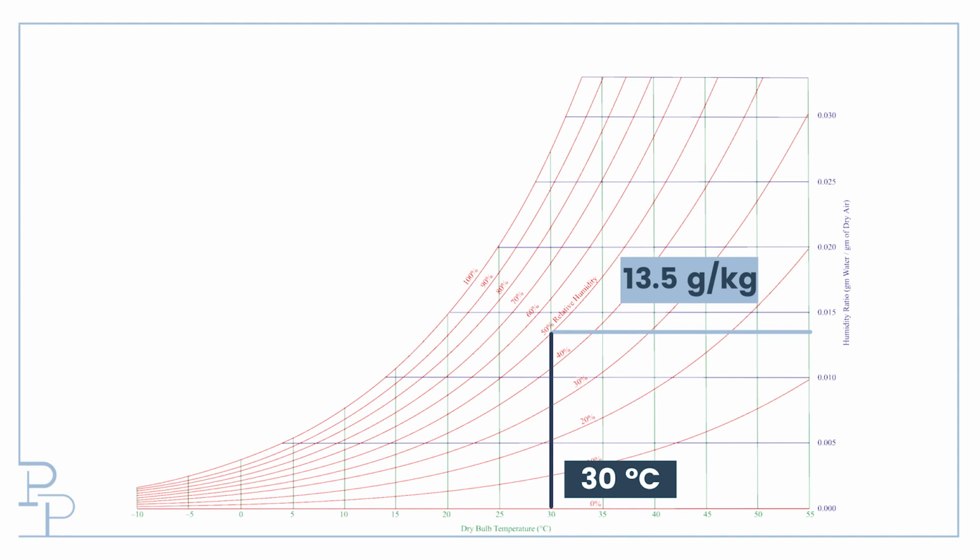If we cool down the gas by dropping its temperature, we move from right to left. When I cool it down, I am not changing the water content of the gas before I form a liquid droplet. The water isn't going anywhere until I get to the saturation curve, so I stay at a constant absolute humidity. However, as I cool down, the relative humidity is going up.